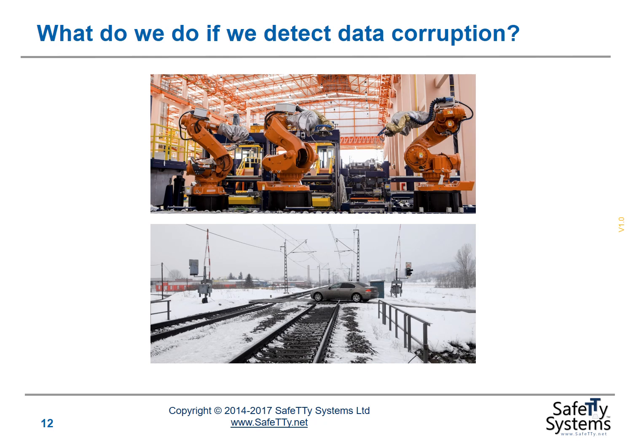It may be a high EMI environment, but we detect data corruption here in our duplicated variables. We can safely shut down the system, probably. So we shut down the system to avoid any potential damage resulting to workers in the factory, people around the robots, if the robots do not behave as expected.